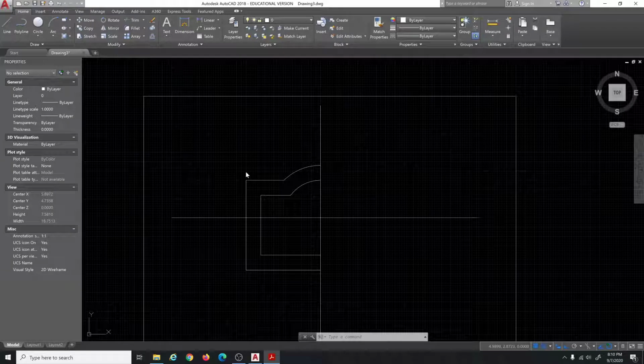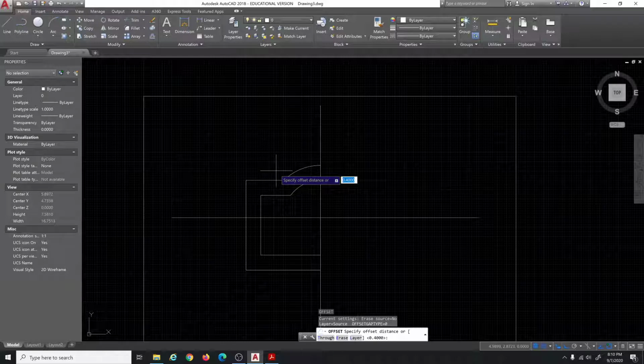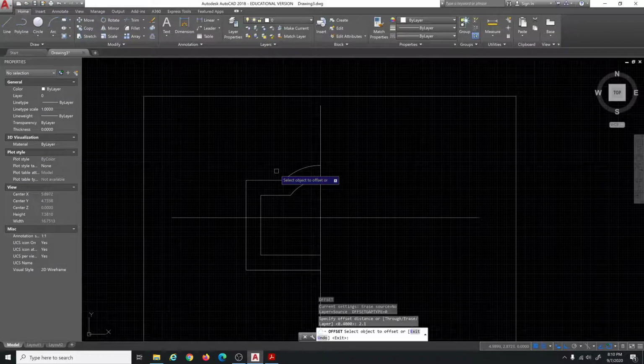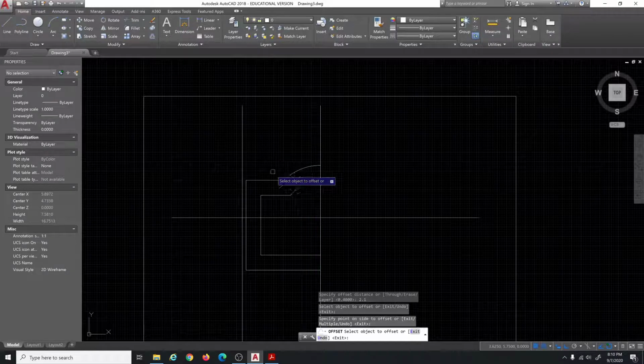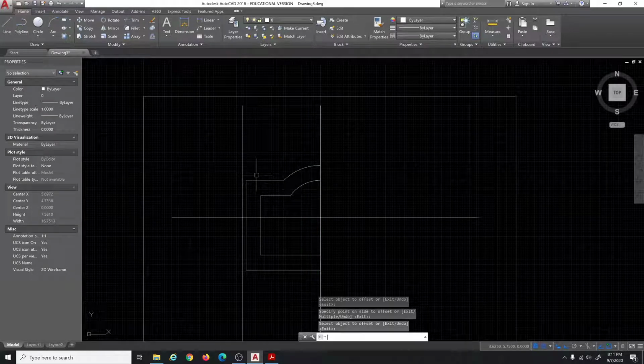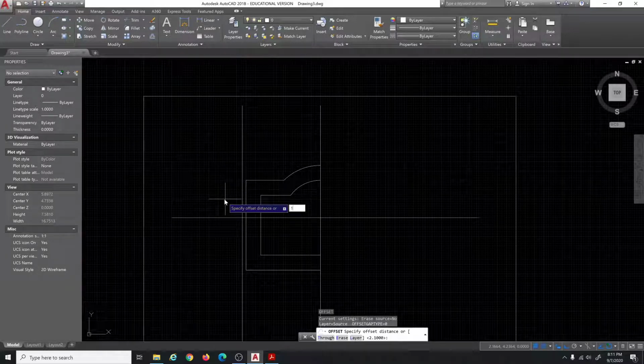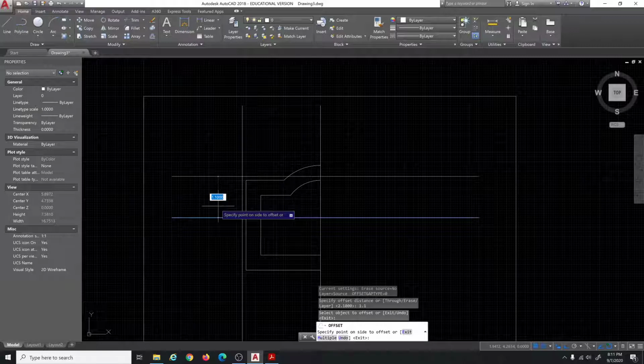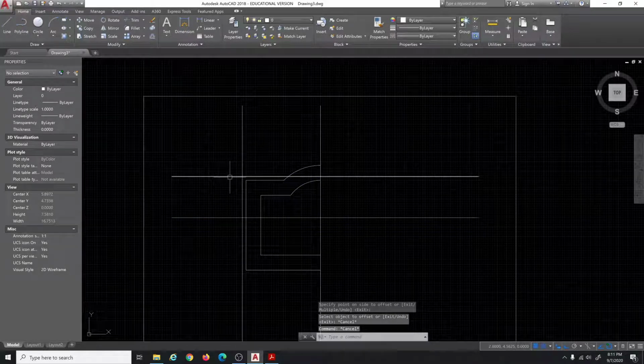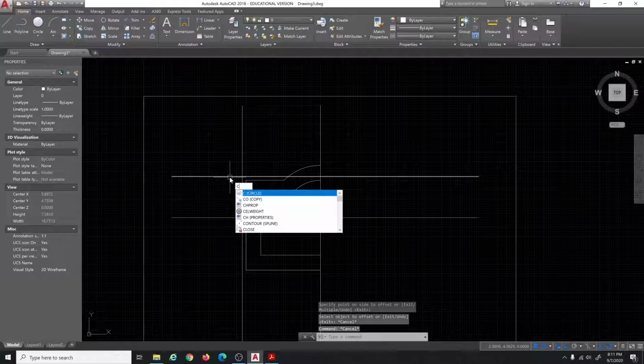Okay, they tell you some dimensions for the center of the little ear. We'll offset 2.1 from this vertical center line that way, and then another offset of 1.1 from the horizontal one, up. Oops, start over here, escape. So offset 1.1, enter, this thing up that way. Okay, that locates the center of the ear, so draw some circles there.